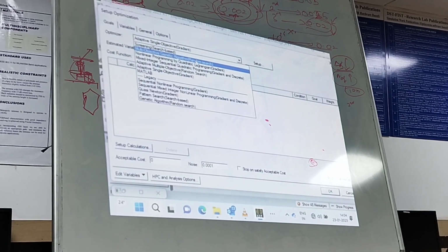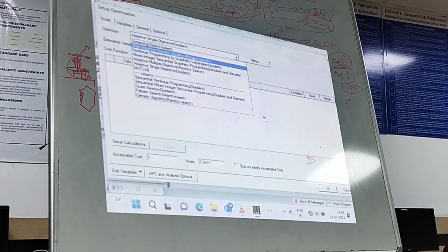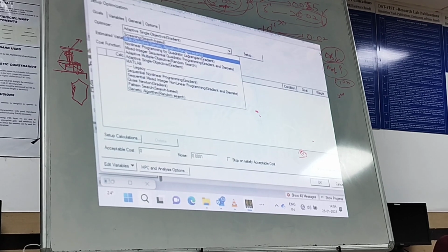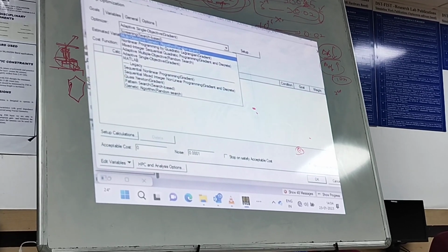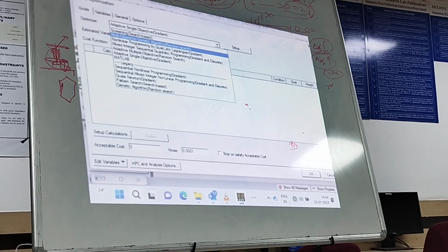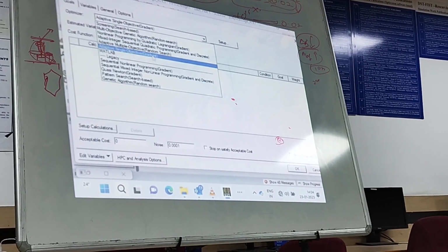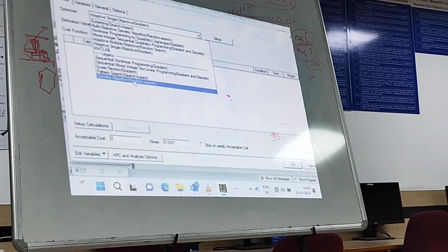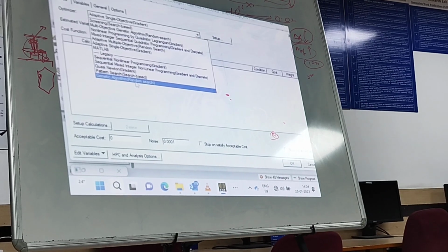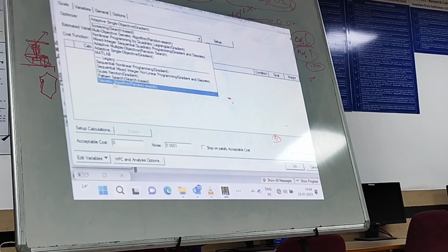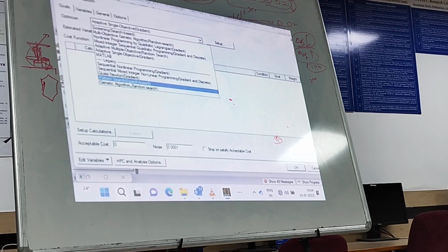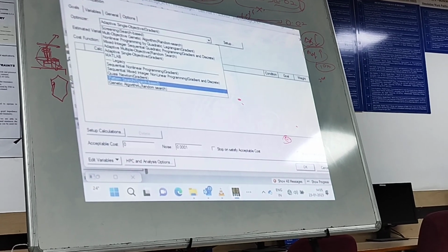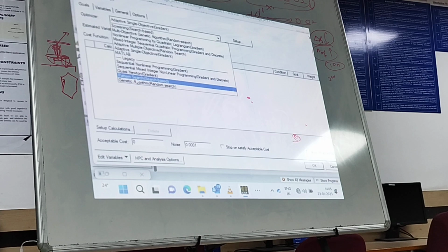If you are going to play with the ground plane, the patch, the substrate dimensions, everything, in that case I will go for a multi-objective genetic algorithm. For every kind of case, we have different kinds of algorithms. Generally, I would suggest a genetic algorithm if you are starting blank and want to go for optimization. The random search or pattern search, if you want to attain a particular radiation pattern or based on your frequency sweep data, this pattern search algorithm will work on that.